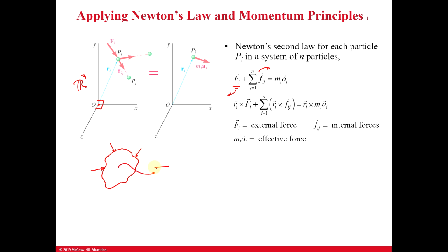Internally, you're going to have stress and strain. We won't compute them in this chapter, but they are all related to the external forces. And they're going to produce internal forces that are going to try to either compress or stretch. That's where in statics we computed compression or tension.